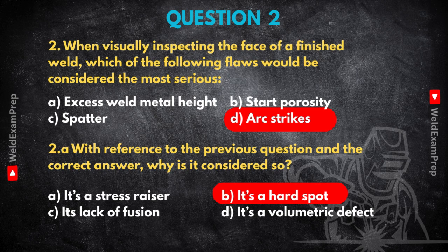So you get this tiny zone, this hard spot that's incredibly hard, but has almost no give. It can't stretch or deform under stress like the metal around it. It just wants to crack. Okay. So it's a weak point because it's too hard and brittle. Precisely. If we connect this to the bigger picture, that hard spot isn't just a surface mark. It's a fundamental change in the material properties right there. It becomes a prime spot for a crack to start. Even under normal loads, maybe stresses the rest of the material handles fine, that brittle spot can fail. And things like residual stress or even hydrogen getting in there, delayed hydrogen cracking, can make it even worse. A tiny flaw initiating a potentially huge failure. That really paints a picture.